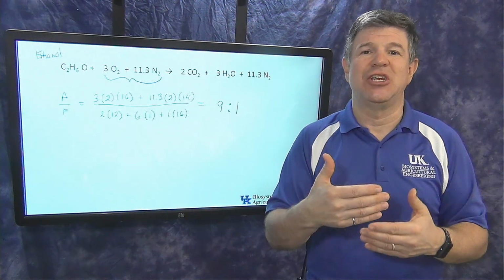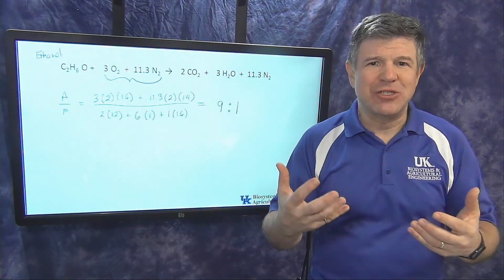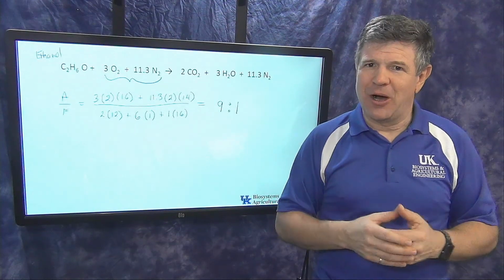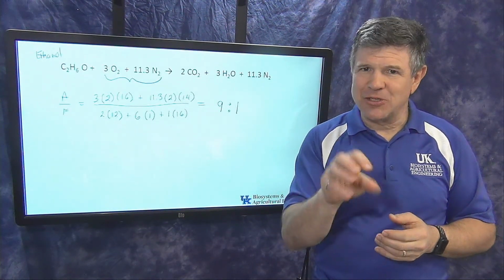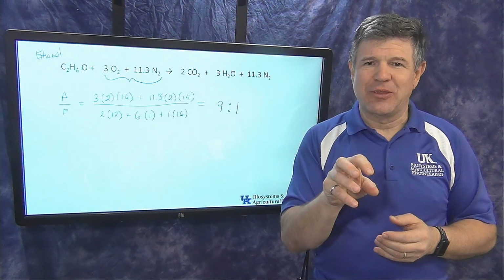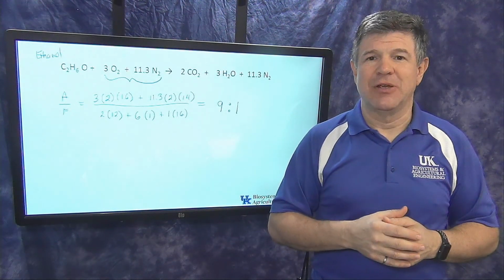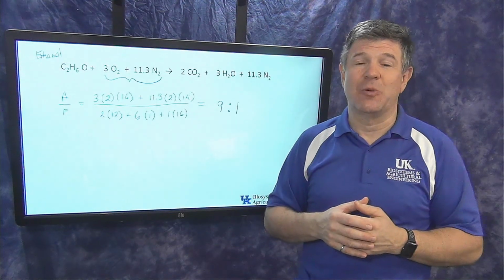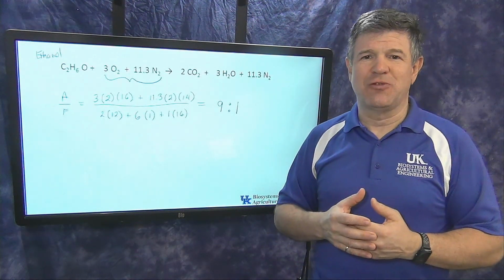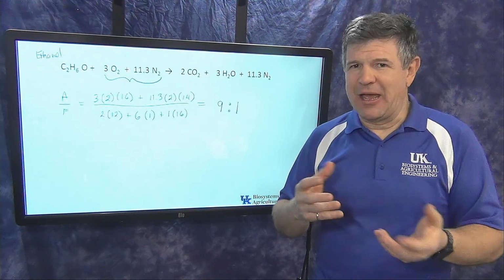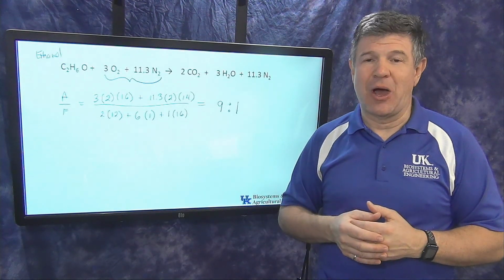So they're actually changing that air-fuel ratio. In those fuel-injected automobile engines, spark ignition engines, they're changing how much fuel they're adding to the air that's going into the engine. And so they can actually compensate for that on the go. But this is why you can't just switch fuels without having to do some adjustments to make it operate well.